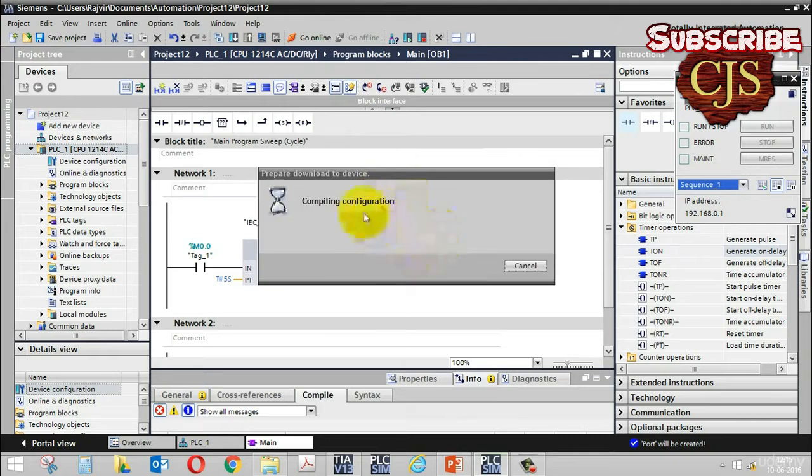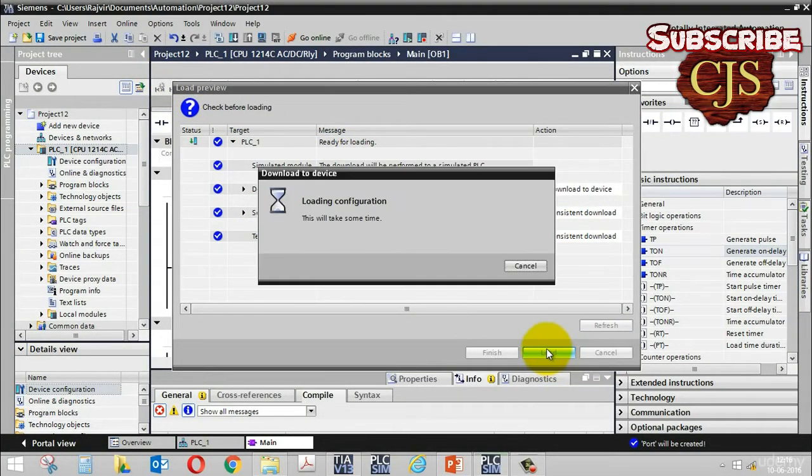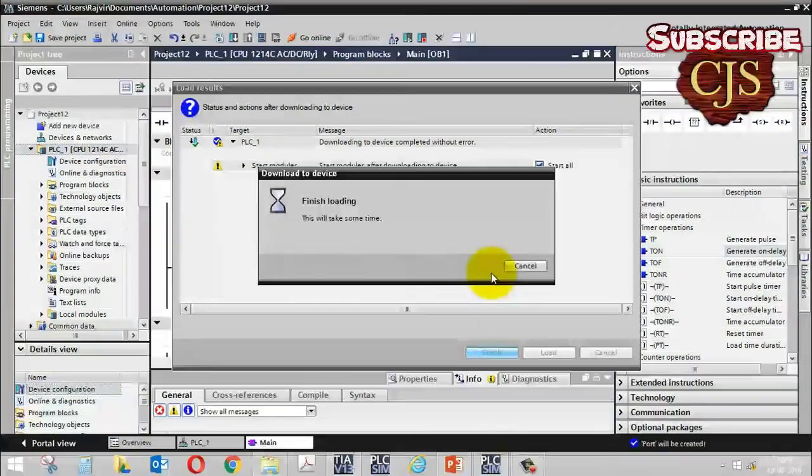All right, you will see this window which says prepare download to device, compiling configuration. So it's compiling the configuration of your PLC, and it has shown the IP address. This is an IP address which it selects automatically for the PLC. Now you'll have this preview window, load preview. You have to click load. So this loading will download the configuration to your simulated PLC. Now it will ask you to start all, so click on start all and finish.